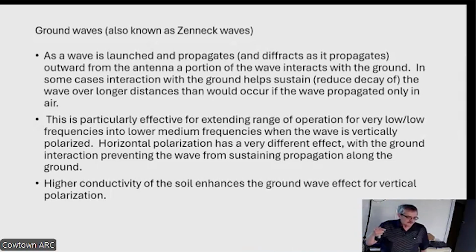Okay. Let's say you've got a horizontally polarized wave, and as it's interacting with the surface, in the case of a good conductor, the electric field that's present will induce an electric field in the opposite direction on the surface of that conductor. That effectively cancels the electric field and forces it away from the surface. That happens to some extent with real substances, not just perfect conductors. But again, that's effective mostly at these lower frequencies.